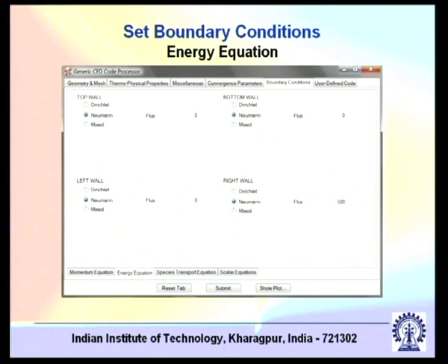We have come across some examples where we had fallen into trouble when Neumann boundary conditions were specified at all boundaries. In this particular problem we will not fall into trouble. Why? Here the problem is a time dependent, unsteady problem, and an unsteady problem can evolve from an initial condition. At time equal to 0 you have a particular value of temperature and that is a unique value, it is not an artificial iteration driven value. If it is an iterative solution, then even for a steady state problem you could start with an initial guess, but that is an artificial initialization. Here you have a real initialization where at time equal to 0 you have a particular value of temperature. Based on that it will subsequently evolve and it will not create any problem for having a Neumann boundary condition at all the boundaries. So do not confuse those examples with this particular example that we are considering.